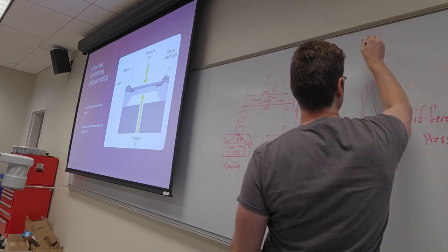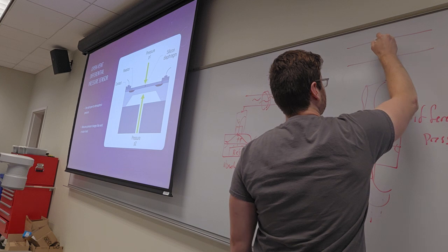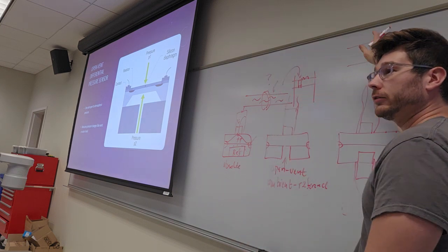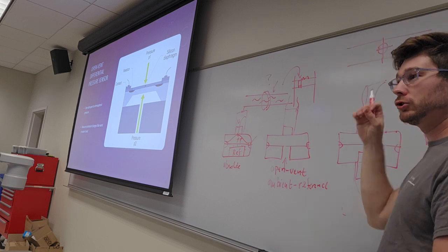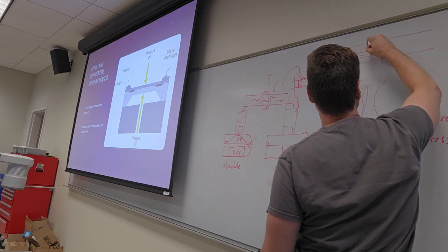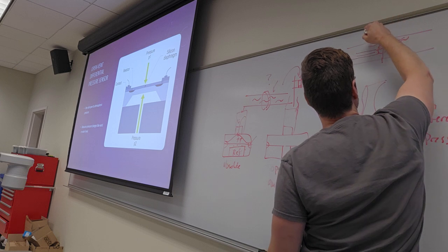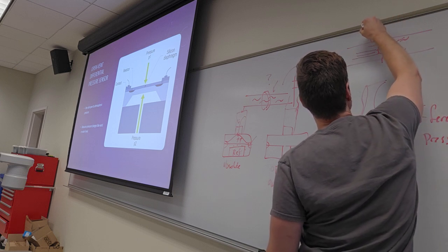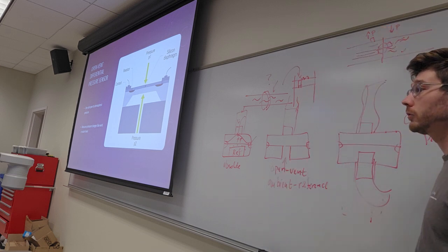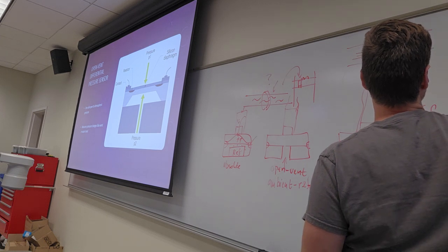Okay, what we talked about before was called a Venturi type flow meter. They often have this weird crosshair in the middle of the tube. Okay, and this crosshair can be really, really thin, but it's just enough to disrupt the airflow. So airflow comes in through here nice and straight, and then it gets disrupted just a little bit. That's enough that the pressure on this side of the tube is just a little bit greater than the pressure on this side of the tube. It's called the Venturi effect. You could achieve the same thing by reducing the diameter of the tube.